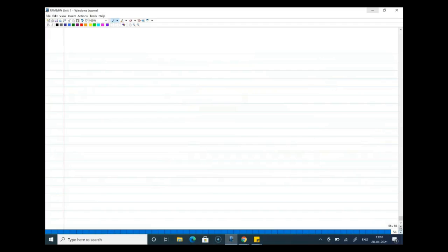If you look at the output of the first stage, we have even order second order intermodulation terms coming at omega 2 minus omega 1 with an amplitude of alpha 2 a square, right? So you have alpha 1 a, along with that alpha 2 a square. That is one term coming there, which is the IM2 product.